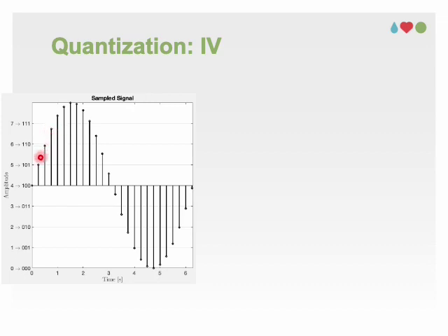This is another sampled value, another sampled value. Let's start with the first sample here that resides exactly on level 4. I'm counting here from 0. Therefore, its quantized value within the corresponding sampling interval, which is this interval, will be 4 in decimal or 100 in binary code.